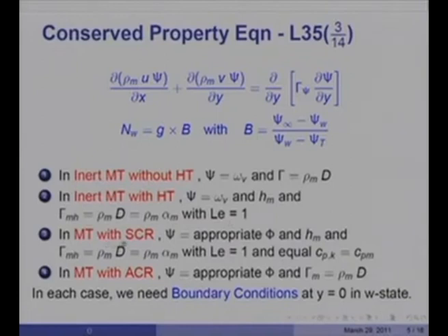In mass transfer with simple chemical reaction, we choose psi appropriately as a combination of fuel and oxygen, or fuel and product, and so on and so forth, and hm, and again make the Lewis number equal to 1 assumption, and also say that the specific heats are equal.